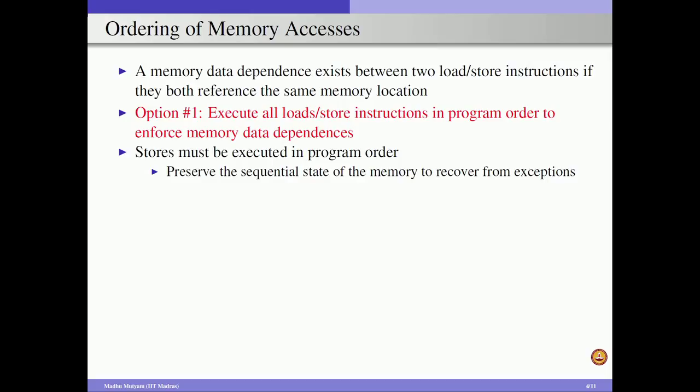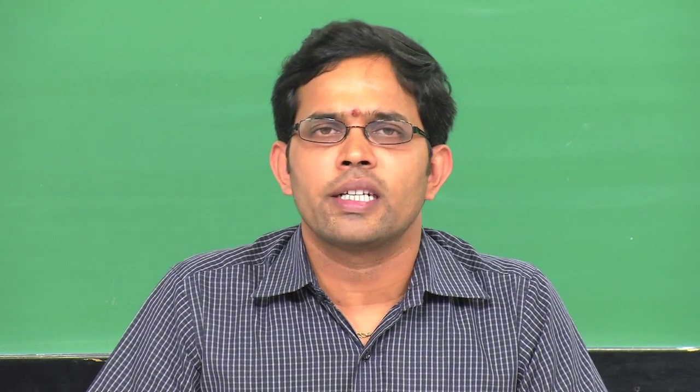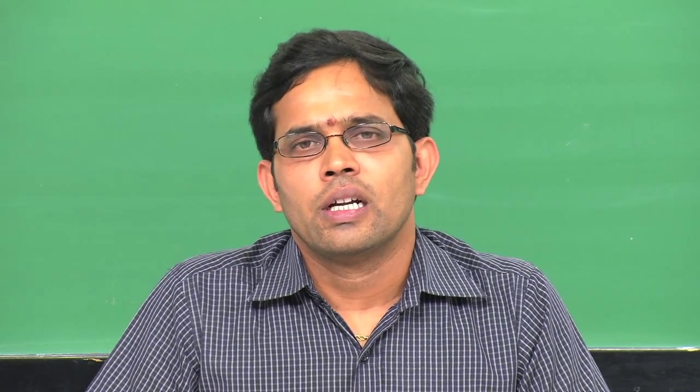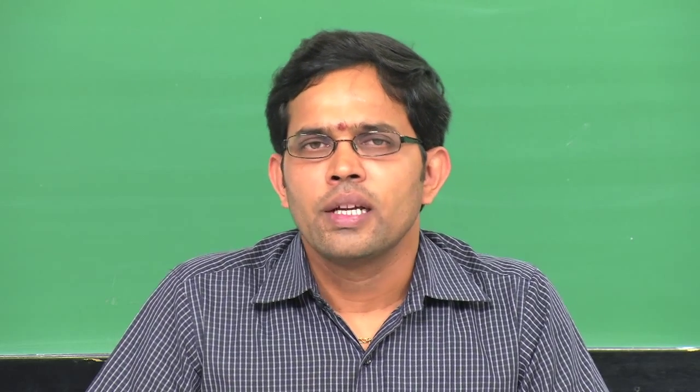So we can relax option 1 slightly by considering this ordering only for the store operations. Once we enforce that all the stores must be completed or executed in program order, we can preserve the sequential state of the memory to recover from any exceptions that happen in our program execution. And in the case of loads, we do not have to enforce this constraint.